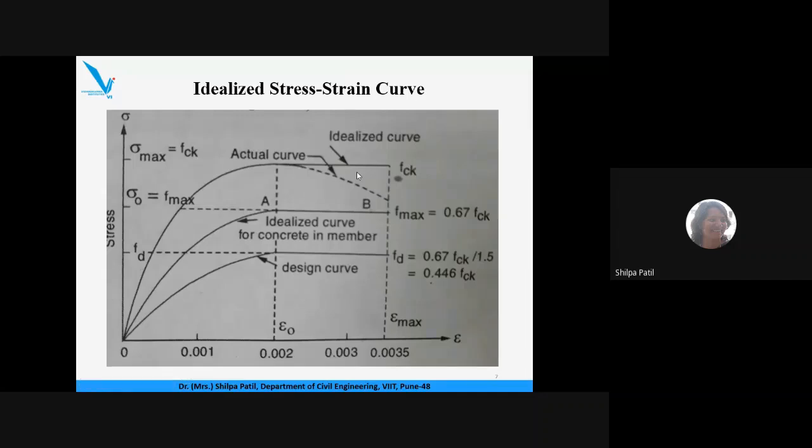Now, compressive strength, when we calculate for concrete in India, we are casting a cube of 150 mm dimension, and we are curing it for 28 days, and we are putting it in a CTM or UTM, compression testing machine or universal testing machine, and we are finding the compressive strength by applying an axial compressive load till failure. This is the procedure, right? Now the rate of loading is kept constant. What should be that value?